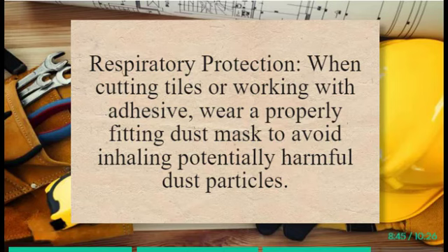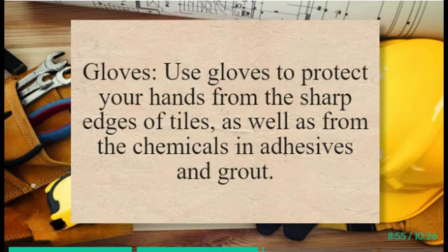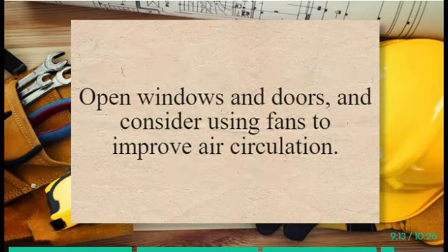Respiratory protection. When cutting tiles or working with adhesive, wear a properly fitting dust mask to avoid inhaling potentially harmful dust particles. Eye protection. Safety goggles or protective glasses shield your eyes from flying debris, tile splinters, and any accidental splashes of adhesive or grout. Gloves. Use gloves to protect your hands from the sharp edges of tiles, as well as from the chemicals in adhesives and grout.